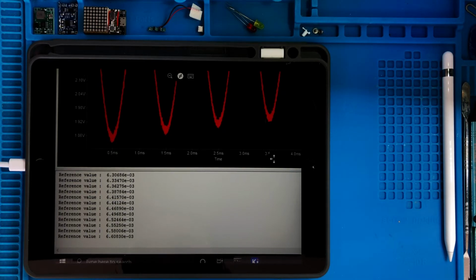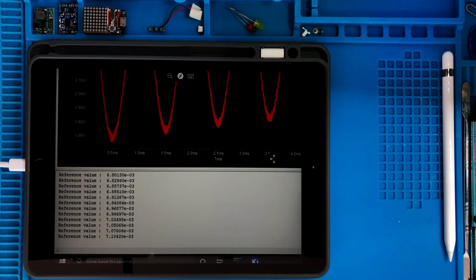From this you also see the importance of understanding what you are simulating. The simulator is not something that you just push a button and then you have the result. Because if you don't instruct it carefully, maybe you will wait forever. Maybe it will hang because you don't put those, for instance, 2 resistors that we put across the capacitors in order to mitigate this divergence for high frequencies.